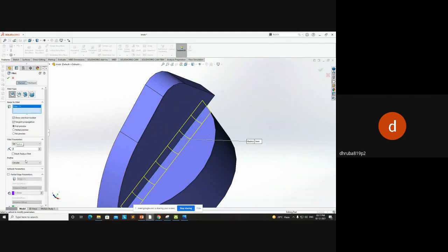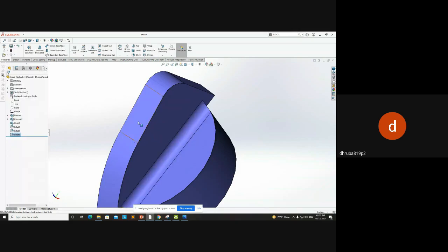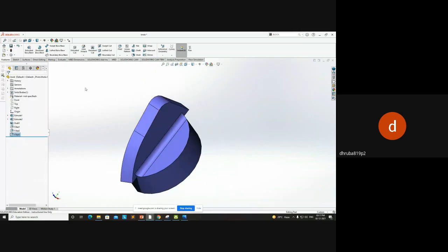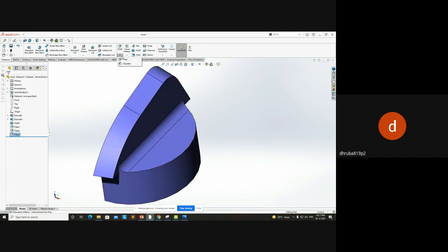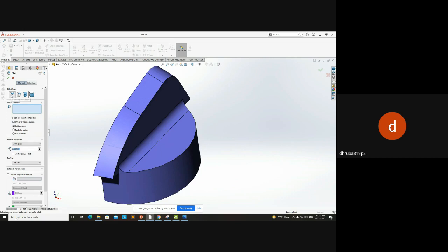And here I'll include under fillet radius 2. In sketch, in order to apply a fillet, you need to select either the point where the two lines are meeting or the adjacent lines. So this is how fillets are created. Now I've shown two types of fillet, constant and face fillet. Now here we have variable size fillet. In variable size fillet, you can vary the fillet thickness.